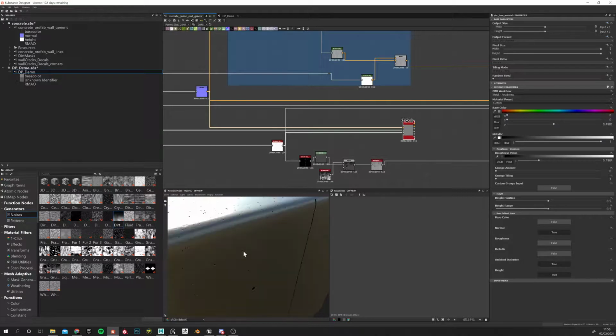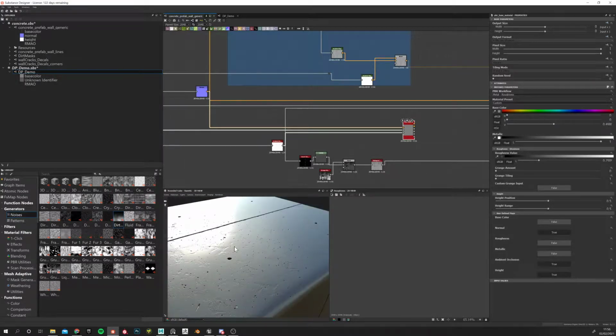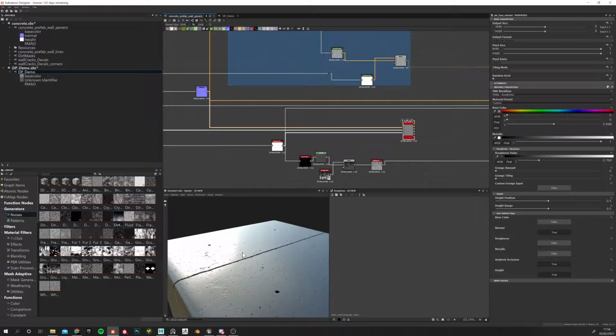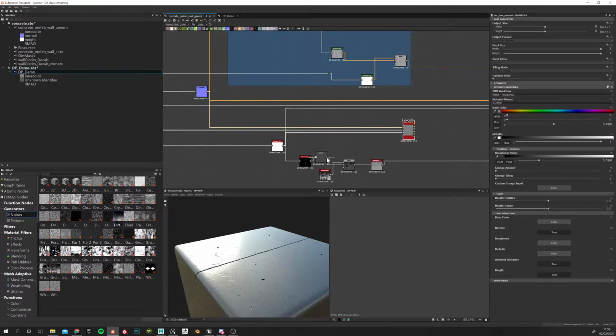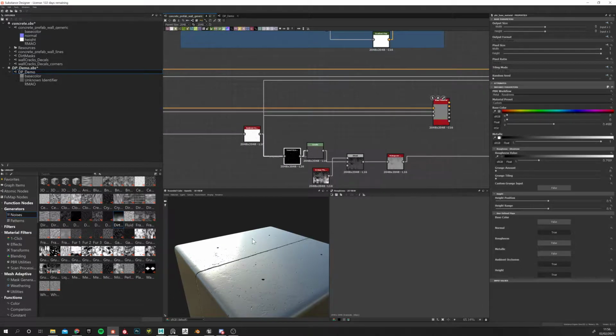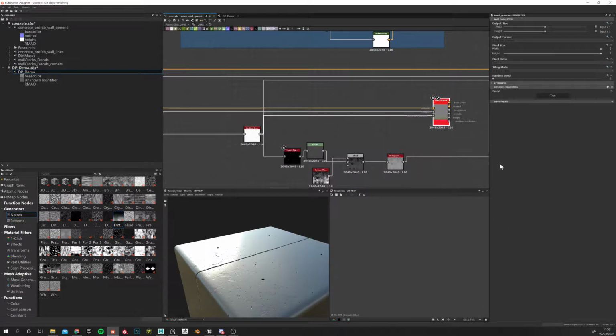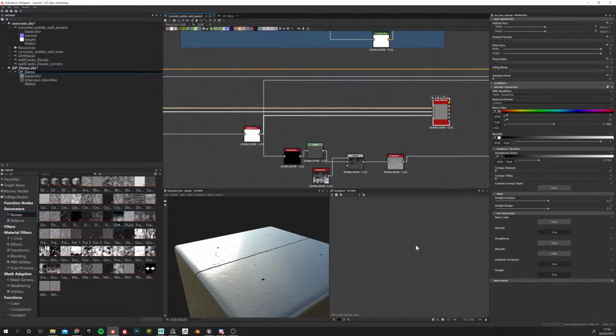And this is where the majority of your issues is, guys, when I see the shader that we have created so far, is that the roughness map is pretty much not really worked out well. So at the moment, the reason this looks like that is because this material preview has a roughness of 0.25 built in. So we need to gray it out to make it look varied. So at the moment, it has a roughness of 0.25 something.